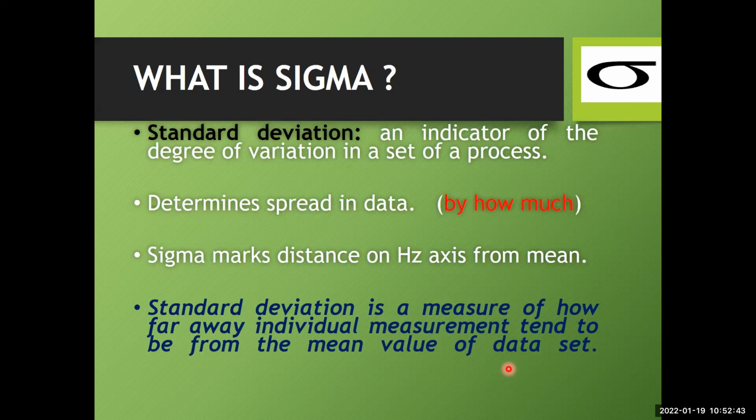My mean of 100 shafts is 100.01 mm. But how much is the spread? What is the standard deviation level? How much are my pieces deviating from that mean value? It means something: if they are deviating heavily, there is some disturbance in the system that needs to be relooked. This is what standard deviation tells us.